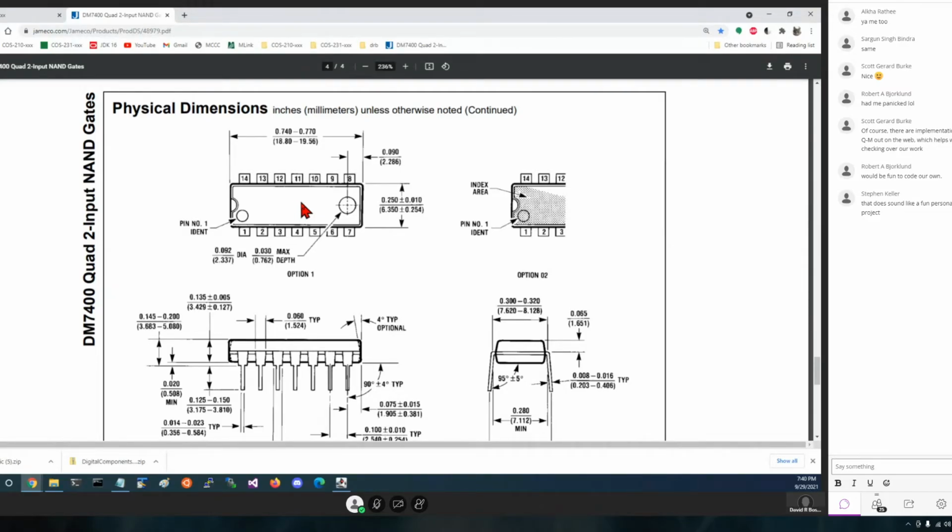Okay, well, if you take all the transistors and the wiring that's inside this chip, it actually fits right in the middle of the chip in a circle about the same size as that little circle over there. Everything else inside here is empty, except there are little gold wires that go from that circle thing in the center out to each of the pins. The most likely thing to damage a chip is either you heat it up so much that the gold wire comes unsoldered internally, or you drop the chip and the little gold wire breaks. But the thing itself, certainly no more than the size of that circle, right in the middle of the chip. The rest of it is just simply plastic, and it has to be this size in order to stretch out the pins that far apart.